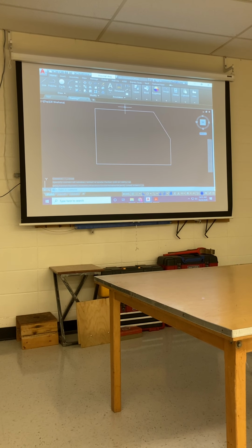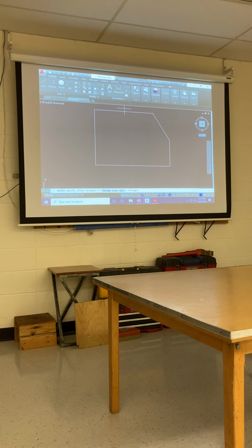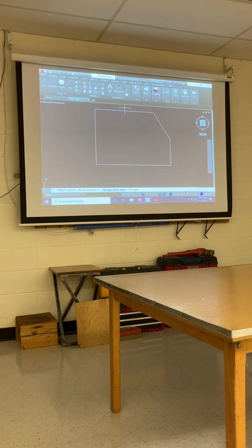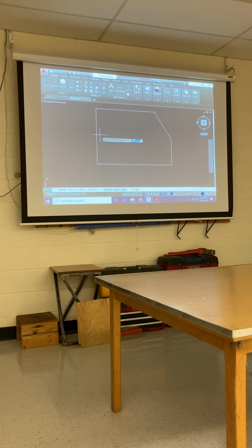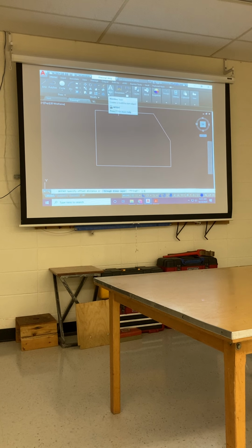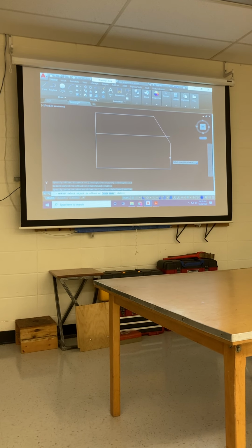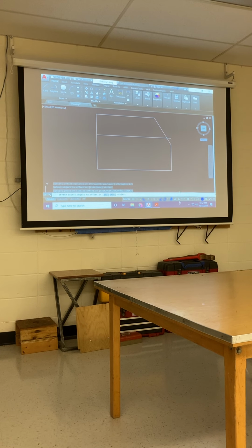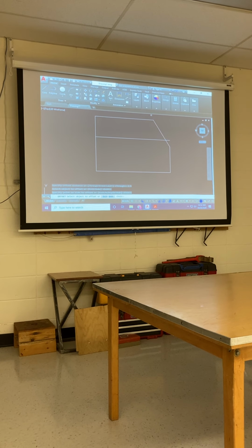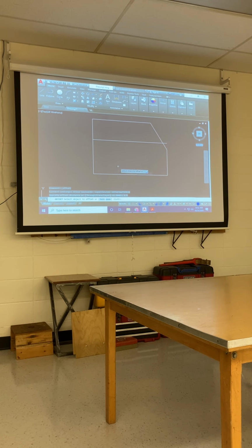Now to locate my centers, here's what I'm gonna use. I'm gonna use my offset command. So I go up to offset. I can look at my drawing and it says 2.5. So I hit offset. I'm punching in 2.5. Going up from here, 2.5. I'm gonna hit this other one over here for this circle down on the right. I'm gonna do that right away, 1.5.